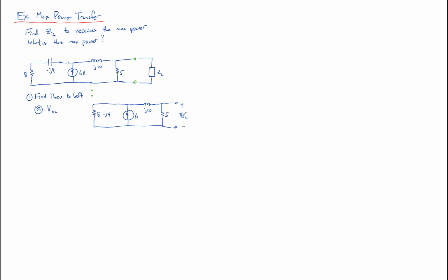So there are a number of ways we can do this. We could do a nodal analysis. If we did a nodal down here, we'd have two unknowns. We'd call this V sub 1, and we'd call this VOC, and then we could solve. We'd have a 2 by 2. That's not ideal. Let's see if there's something else we can do that's simpler.